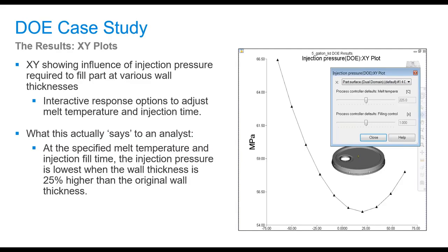So if we remember, the nominal wall was 1.5 millimeter earlier, and it doubled at the pour spout region. Did we need to increase that wall thickness as much at the pour spout region? So really this means the wall thickness increased from between 5 and 35%, which is quite a bit. So at the end of the day, how much thickness offsets the flow leader restriction is basically what this says.